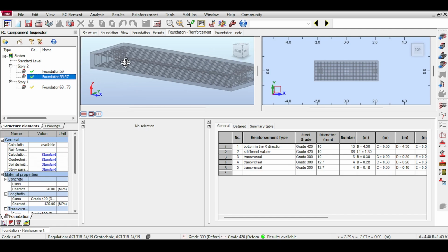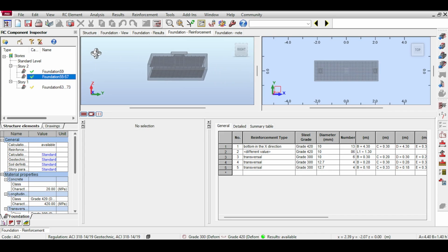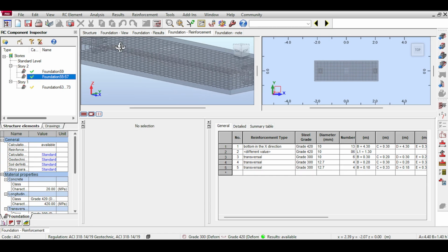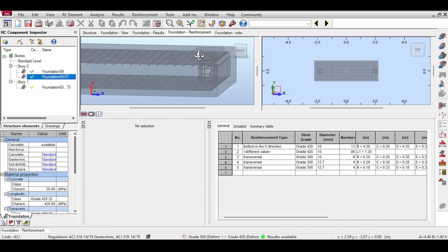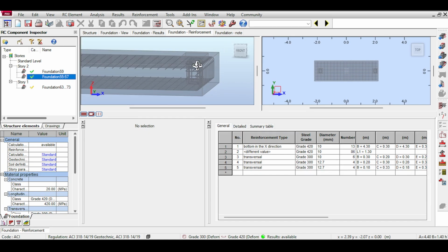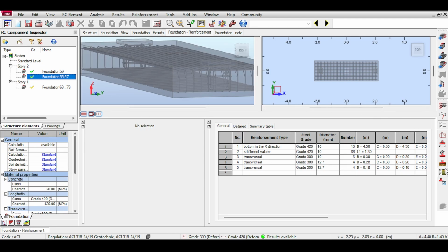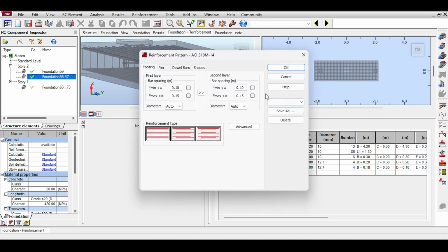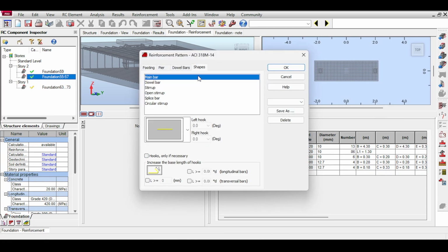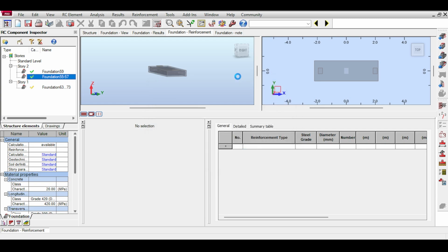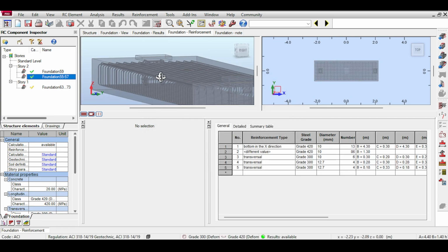Usually it's different. Well, that's odd. Usually we have our secondary reinforcement being caged and our main reinforcement not being caged, not the opposite. Like here it's taking the main reinforcement and caging, making a box, and the secondary reinforcement just levitating. I can just force it by going here. This is out of back and forth. You can just ask it for hooks and go for hooks and hit OK and then run again. Of course, now I have done too much damage. Yeah, okay, this is at least something I have seen.